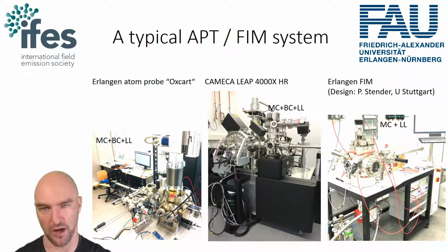And this is also why we have a load lock and possibly a buffer chamber, because a load lock allows us to interface to air. Air has moisture in it, and the moisture is going to absorb on the walls of your chamber. So we can pump down the load lock to a low pressure, and then go from the load lock into either the measurement chamber or buffer chamber.